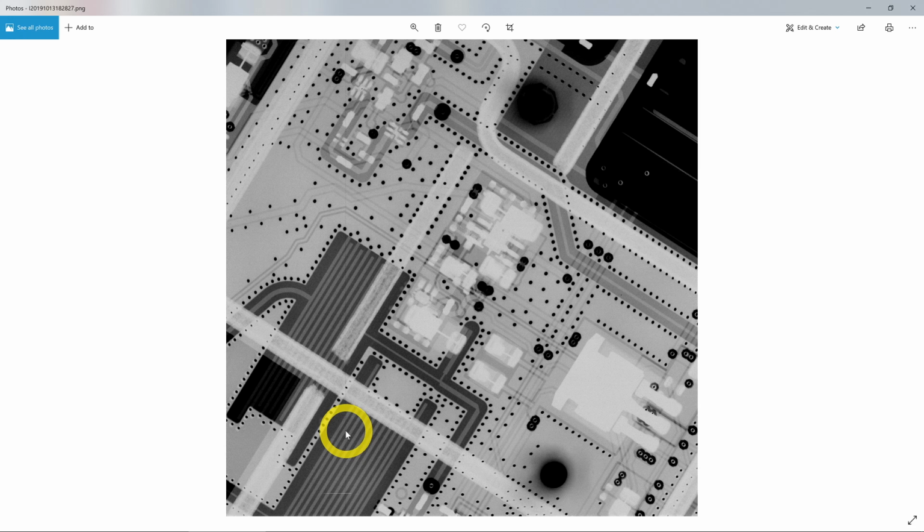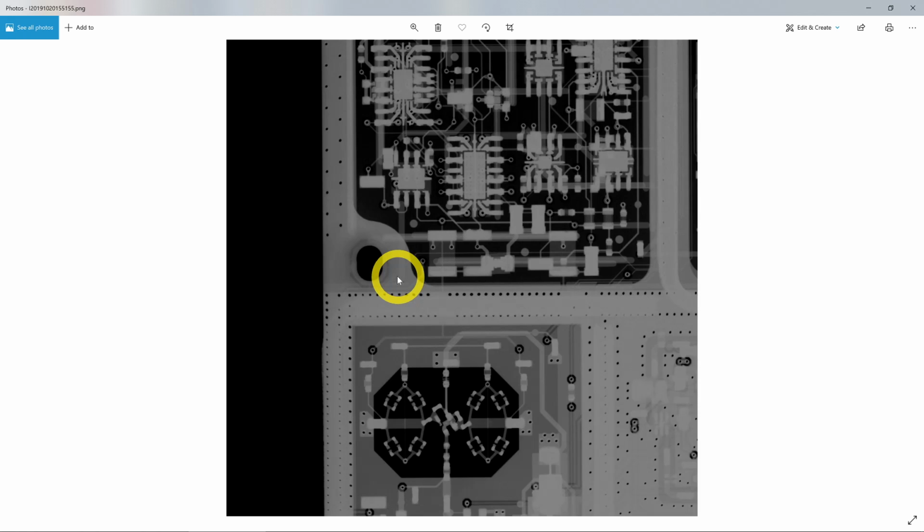But at the same time, it gives you a really isolated design, and then all the cavities that are formed by the chassis and the top and the bottom of the board, they don't matter anymore. So there's some advantage to that as well. You can see that indeed they have buried filters in the layers. The other part that's interesting to look at is the VCO core.